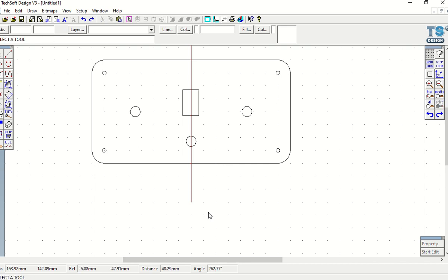Right, other things that I want. Now, I would like to indicate the outside of the 3D printed box. Now, when we print with a 3D printer, we don't want to be printing things flat in regards to like the top and the bottom of the box. We only want to be printing the sides.